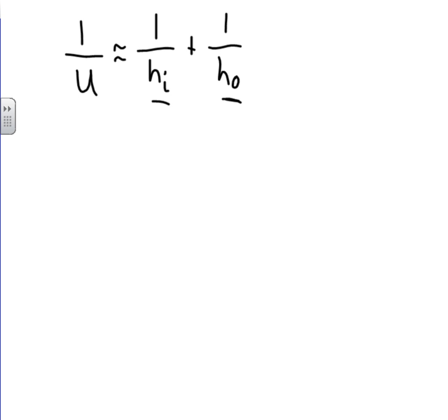Okay? So that is the heat transfer coefficient that you get from the flow in an annulus. So this is an annulus flow. And when we're doing annulus flows, because it's a non-circular geometry, the first thing we'll have to do is find out what our hydraulic diameter is.